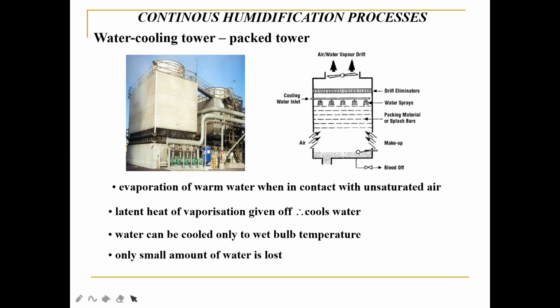Actually, a cooling tower works using the concept of evaporation. When the warm water comes into contact with unsaturated air, there will be latent heat of vaporization given off, and this will cool the water in the cooling tower. The water in the cooling tower can only be cooled down to the wet bulb temperature.